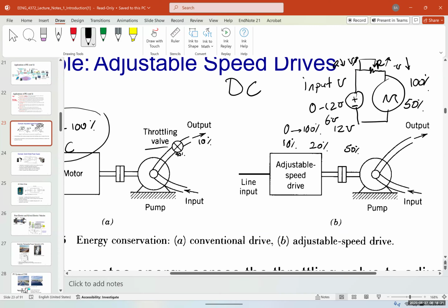The larger the resistor is, the more it's going to consume; it will have a higher voltage compared to the smaller one. So now imagine that we want to run this motor at 10% for half an hour, then 90% of the voltage would be on the resistor. And if it's not a good resistor, it's going to melt down. So that's one problem. You need to have a heat sink. It's going to be very difficult if it's a high voltage.